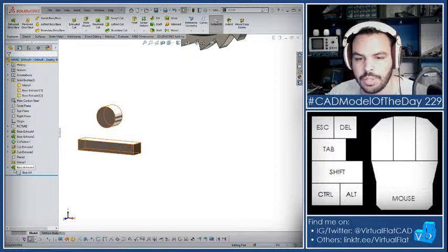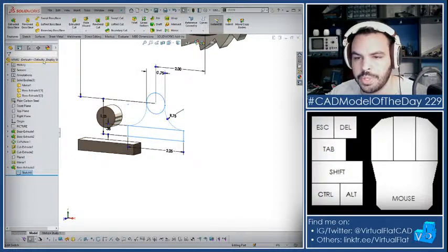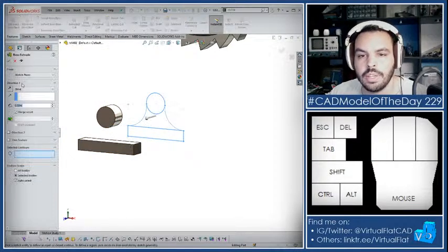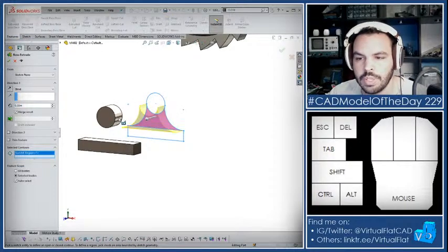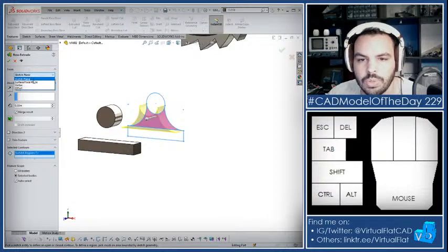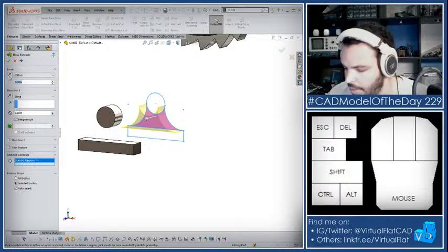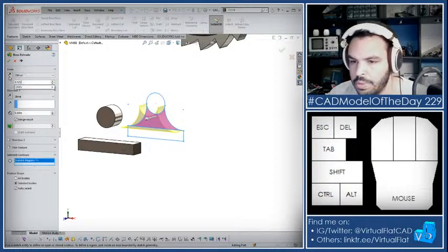And then I'll actually go back into the sketch, grab it again, hit extrude, because now what I can do is grab that other contour and let's say, can I say offset from, well, I'll just say offset 3.125.